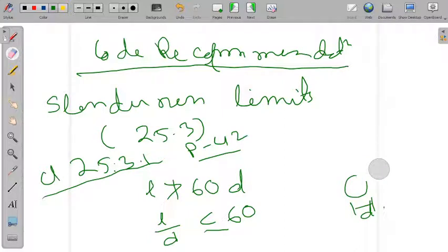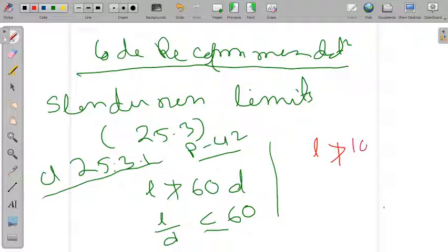Then the other condition under this is that if in any given plane one end of a column is unrestrained, basically talking about the cantilever column, its unsupported length L shall not exceed 100 b square divided by d.